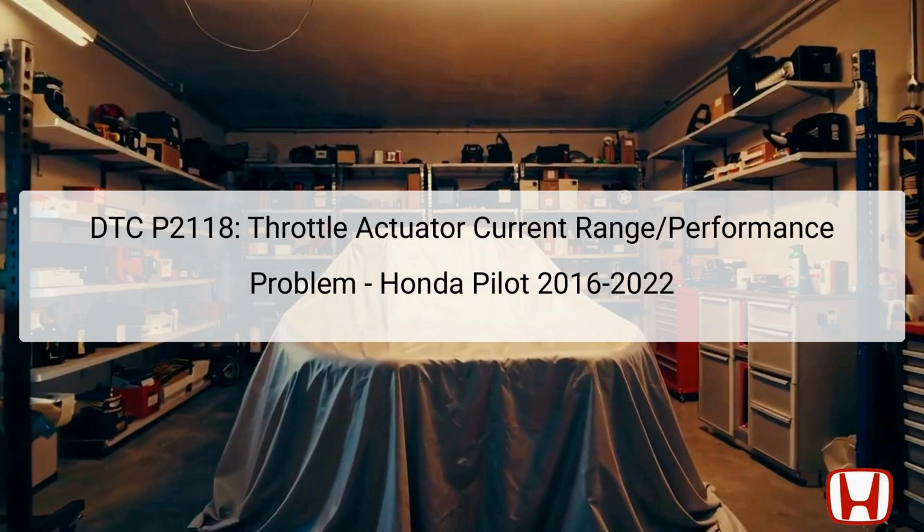The throttle body is the primary component involved in this issue, receiving signals from the powertrain control module, PCM, to regulate airflow based on accelerator input. The actuator is designed to adjust the throttle plate's position accurately, but any discrepancies can trigger the DTC P2118.